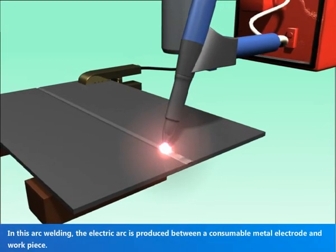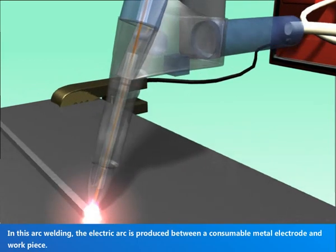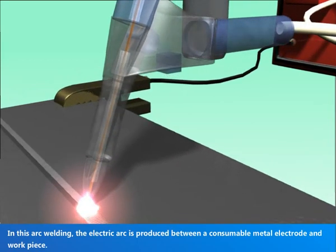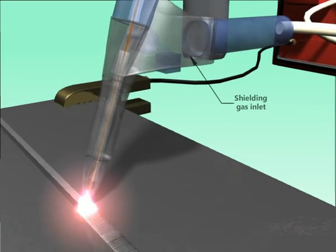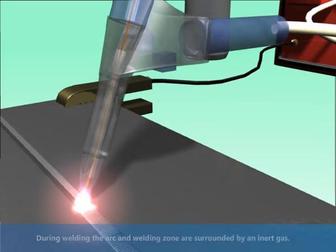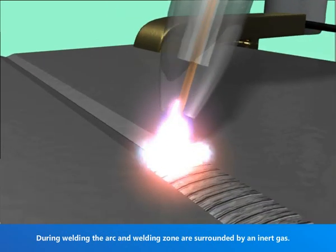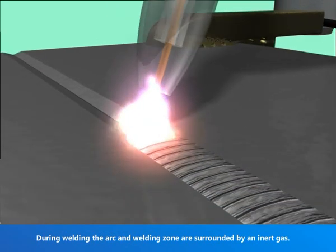In this arc welding, the electric arc is produced between a consumable metal electrode and workpiece. Shielding gas inlet, consumable electrode, contact tube, shielding gas. During welding, the arc and the welding zone are surrounded by an inert gas.